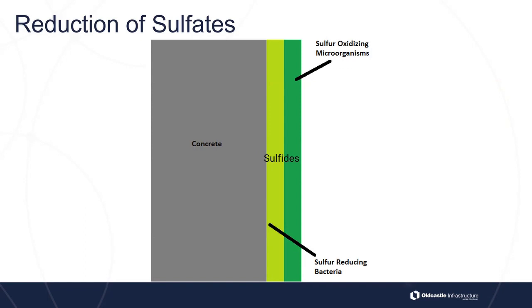So any sulfides that escape the biofilm can undergo a chemical or biological oxidation in the aqueous phase before they are released to the gas phase is even possible. So under anoxic conditions, or conditions where there is no dissolved oxygen in the water, these sulfides will diffuse out of the biofilm unimpeded and partition back into the waste stream.